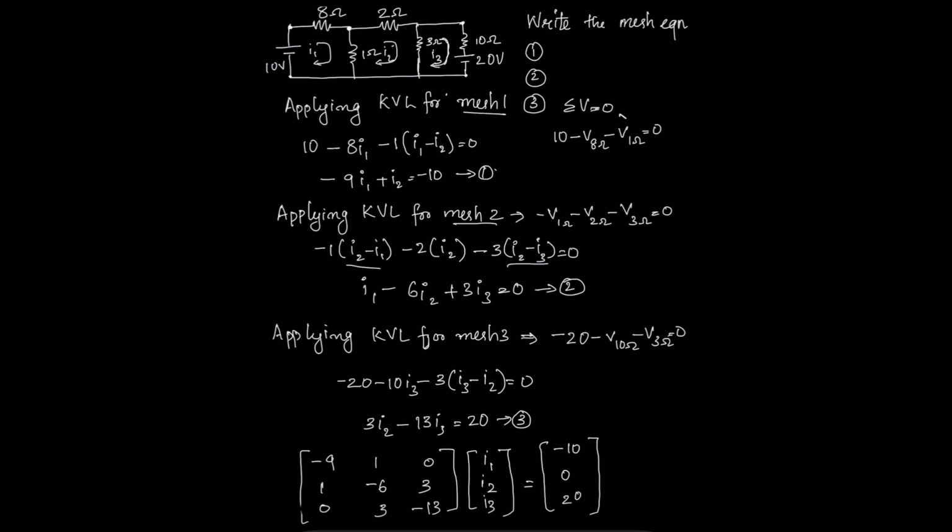To avoid common mistakes, you have to double check the conventions, whether it is a rise in potential or a potential drop. Ensure the shared components have the correct polarity. Let's stop the mesh analysis session here.